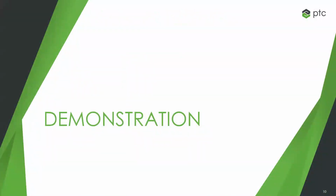And again, I'll go through and show what this all looks like within the context of Creo here. We'll walk through a basic workflow of what it looks like to start with a point cloud, bring it in, clean it up, get it into our environment, and then create some surfaces off of that.